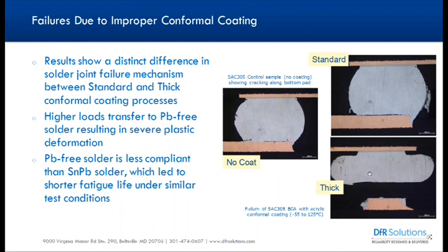So in order to prevent that, some people know they can't prevent it, because the conformal coat is a very thin material, so it wicks underneath. It has like a capillary underfill effect as soon as it goes in there. So basically, if you even have the side of the BGA exposed, it'll go there. So people are saying, well, we'll just mask out the BGA so we know that there's no conformal coat underneath it. But if you apply it correctly, there shouldn't be any problems.